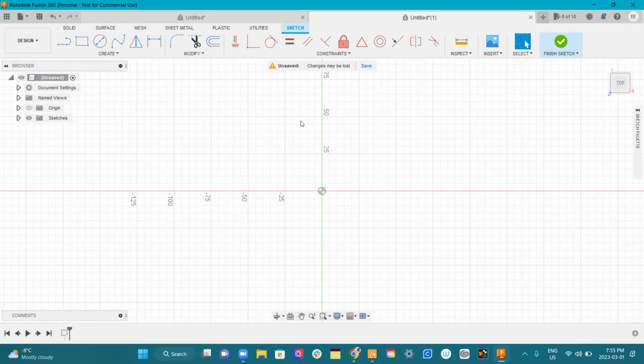But on the back of the machine, it says X motor, Y motor, and Z motor. The Z motor is always the vertical one, but it can be a bit confusing about X and Y. When you go to line your machine up with the thing you're trying to do, say something long, it matters which way it's oriented. So you look at the motor that says X and follow it out, and you know that X is one direction, Y is the other direction.